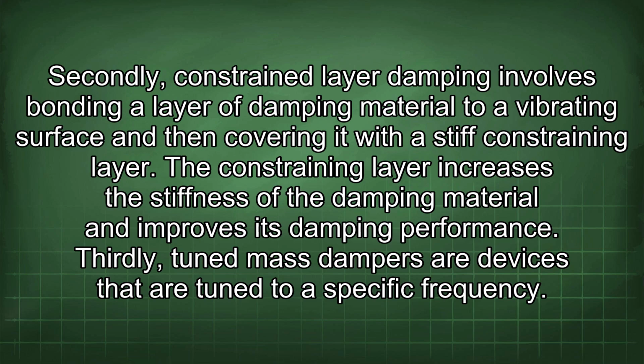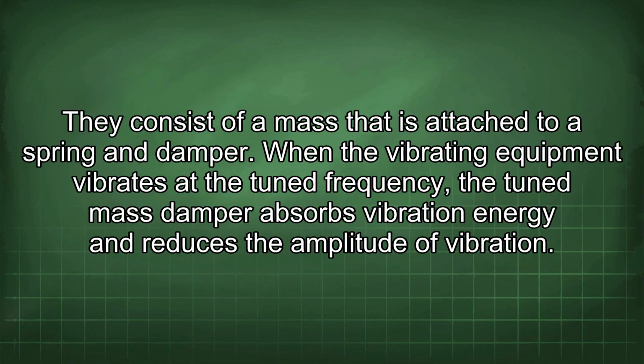Thirdly, tuned mass dampers are devices that are tuned to a specific frequency. They consist of a mass that is attached to a spring and damper. When the vibrating equipment vibrates at the tuned frequency, the tuned mass damper absorbs vibration energy and reduces the amplitude of vibration.